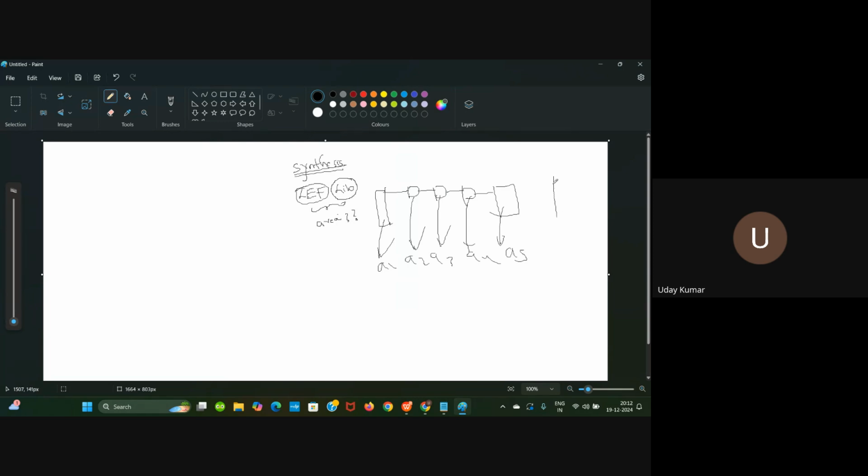If you're using some ROM and you're reading from this ROM or writing into the ROM by processing it, let us be somewhat creative while we're discussing things. You will also have the area of the ROM or RAM. The tool will add all this and give you the total standard cell area. And you can get this in the synthesis stage itself.